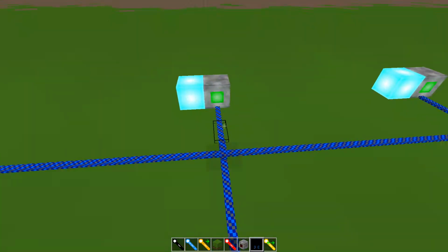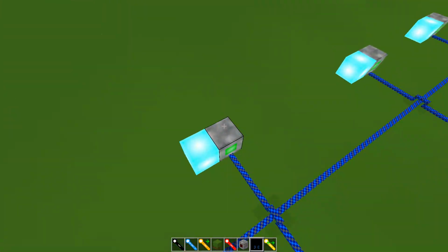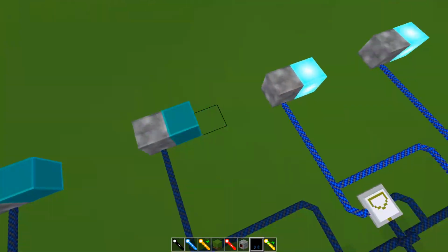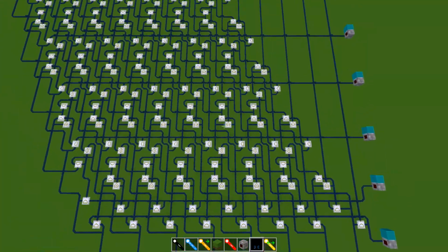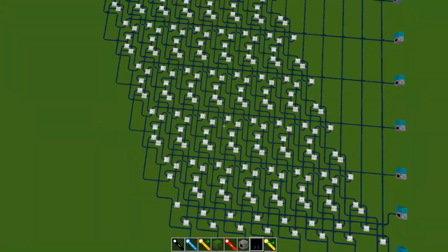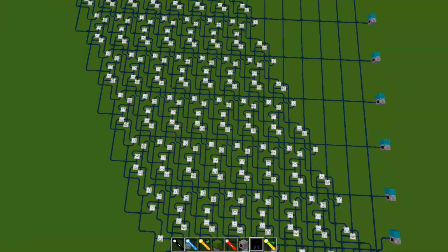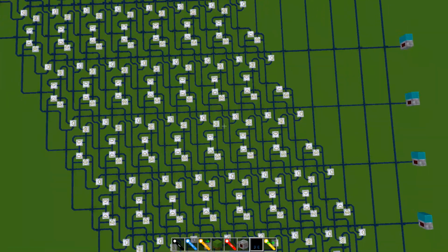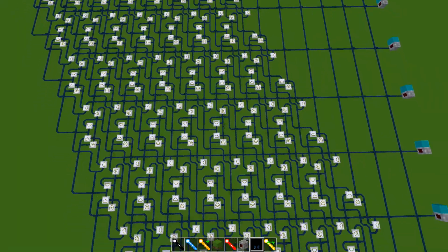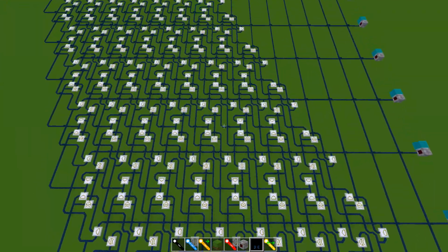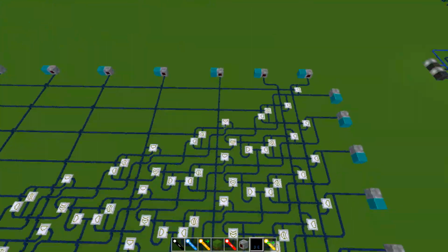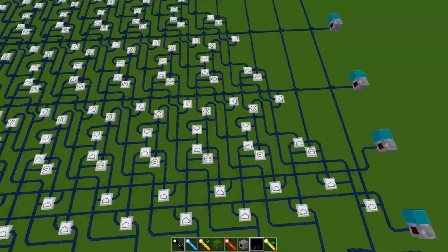Right. And then now I will take a closer look at the circuit and explain the functionality after I've turned off these inputs. Now, as you can see here, the way this multiplier works is that it has a series of full adders, the input of which is always the result from the previous full adder, and the other input being a bit shifted version of the input here. And the bit shifting always moves one step to the left for each of the bits, the number of bits.